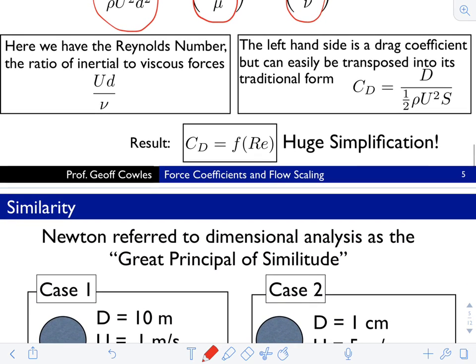So here we have this Reynolds number, and again, this parameter arises if we take either a scaling analysis or even simply the Navier-Stokes equations and non-dimensionalize the terms of that equation. You find that the ratio of the inertial terms, the nonlinear terms, to the viscous terms ends up being a ratio of this form: a velocity scale times the length scale of your problem divided by the kinematic viscosity, which is a property of the fluid. So two kinematic quantities, or rather a kinematic, a geometric, and a property of the fluid.